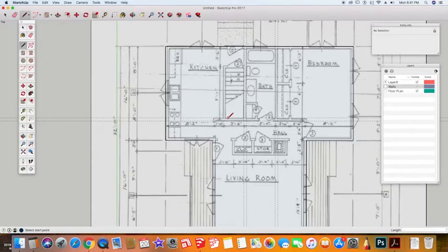So I know that I'm going to eliminate this wall here. So it's really up to me on where I want to start this wall. Maybe I want this to all be open, pretty much to the living room. So I'm actually going to start my wall here, and I'm going to pull across to that here, and then I'm going to pull from here to the up arrow to there, and I'm going to come across again on the red axis, click there, and then I'm going to let my inferencing show me where I need to put things.